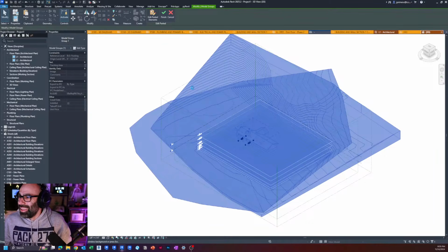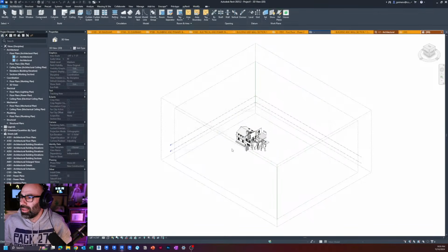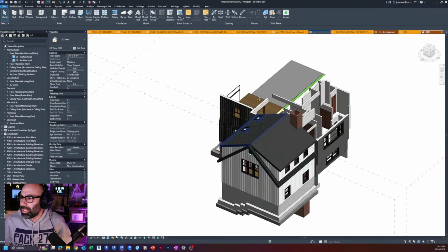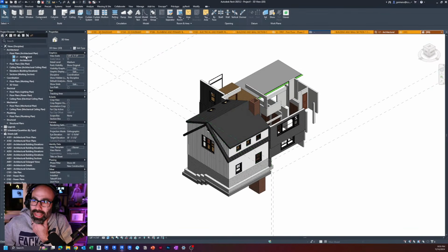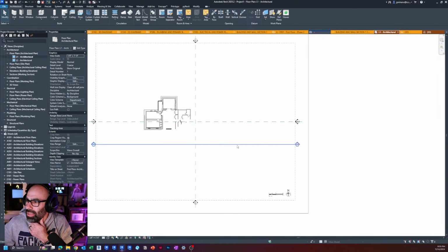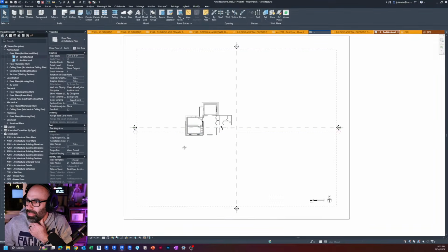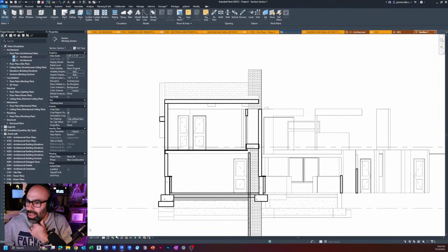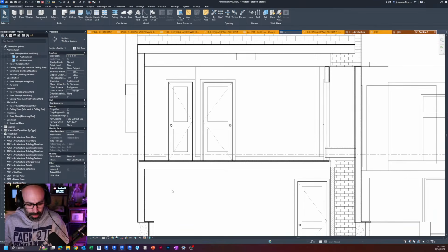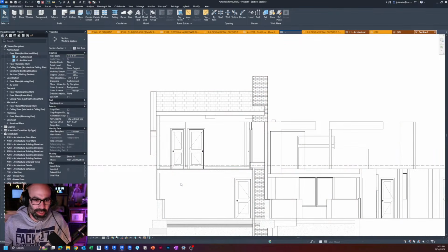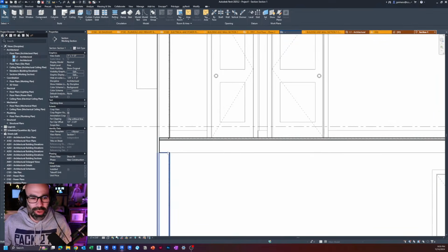Okay. So I placed it, or I attempted to. It's going to delete some stuff because of whatever. Okay, so you can see now it's brought into here. Fine. Okay, so the way this is done is it's actually fairly simple. So I'm going to take this section that was in here, and we'll do it in a section view. And we'll turn this to fine. We'll turn it to, let's say, a 3/8. Maybe do a 1 inch. There we go. Ugh, can't do this without any of my settings. That's okay. So you can see we got walls, doors, windows, right?